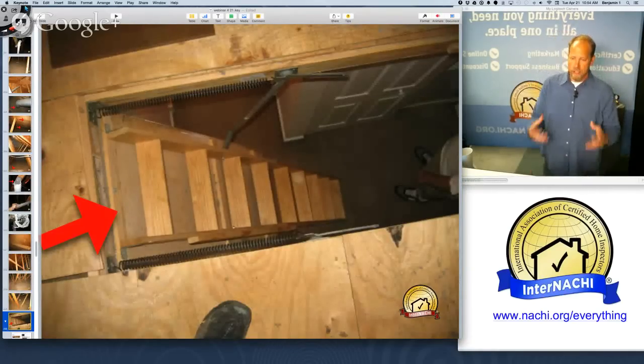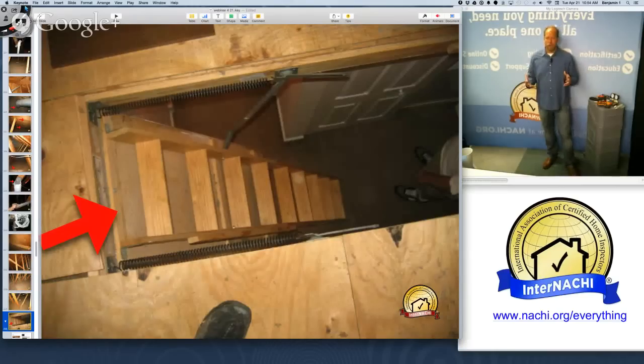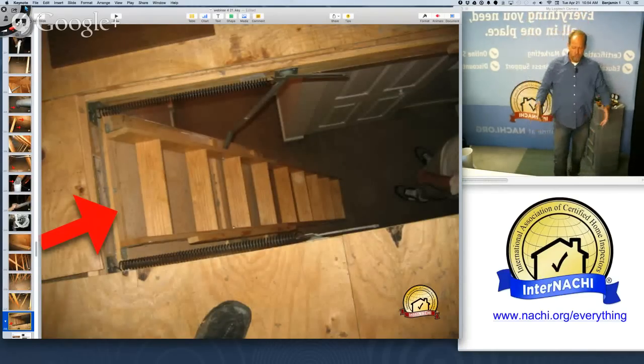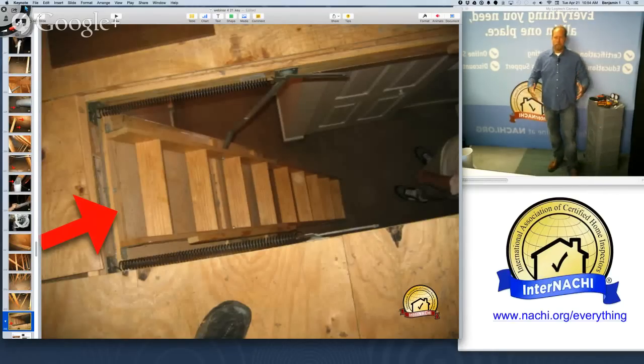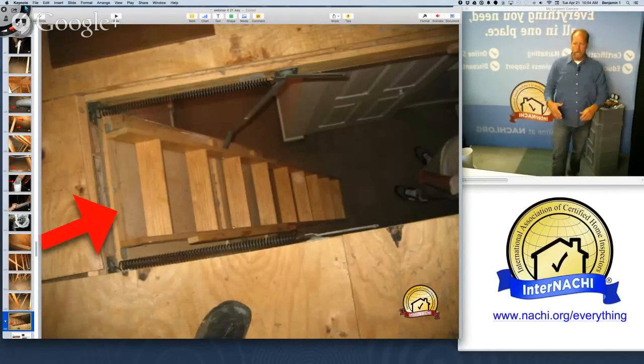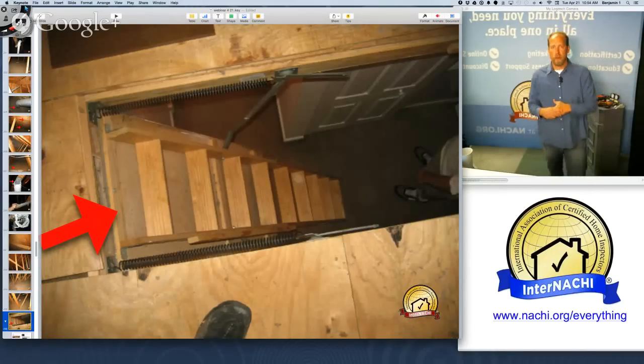But this is essentially a large hole that's allowing the home to lose conditioned air through a natural stack effect. Homes and buildings, commercial buildings as well, have this natural draft that goes vertically, because of stack effect. And we teach this in our building science and energy courses.